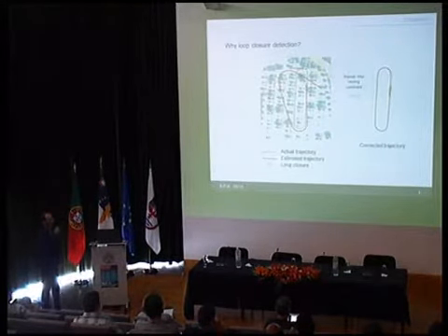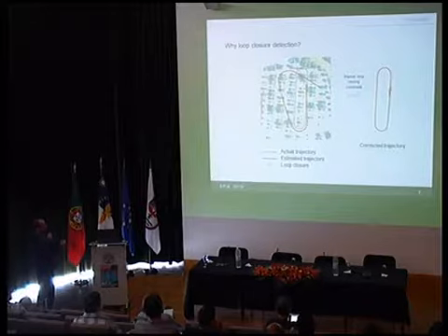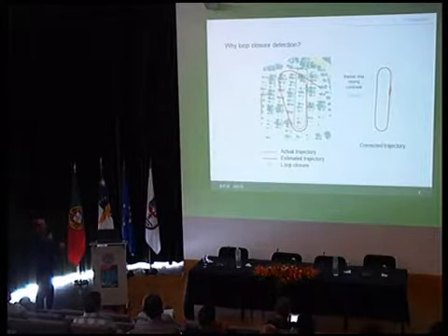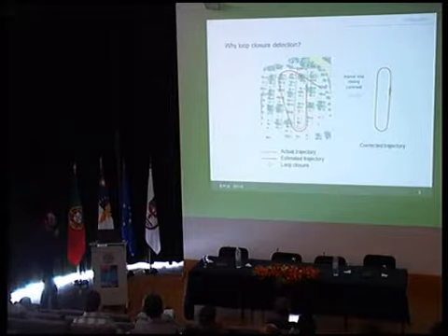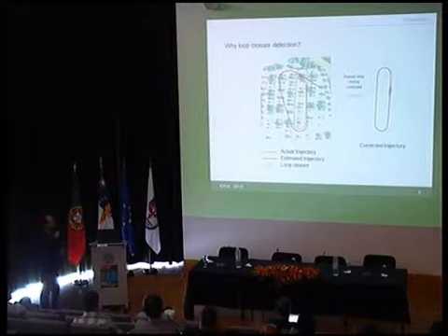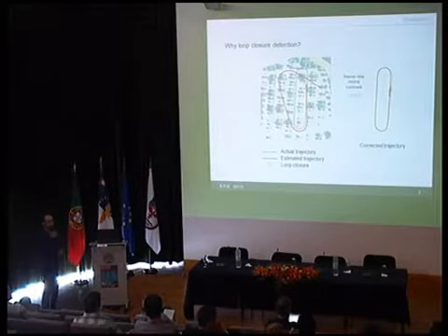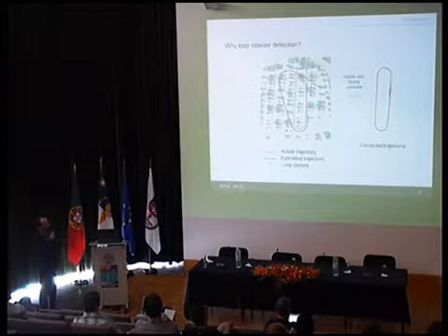On the other hand, if we're looking for loop closure events, we may notice that when we arrive at this place, we are in a place which is very similar to a past one, and if we conclude that those places are the same, we are signaling a loop closure event. If we can do this successfully, then we can correct the previously estimated trajectory. I mean, we can impose that constraint and arrive at this new estimated trajectory.